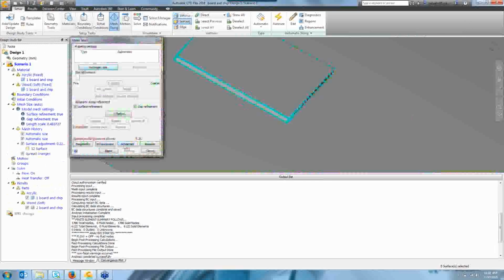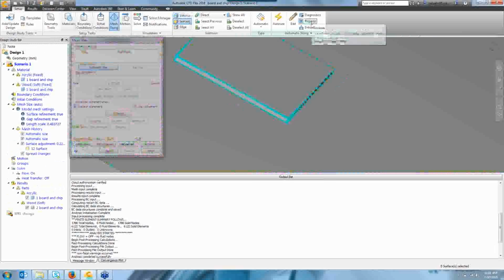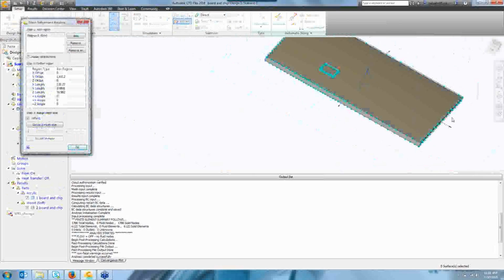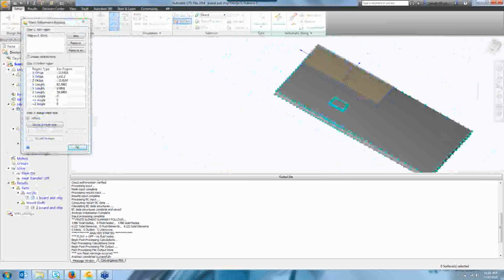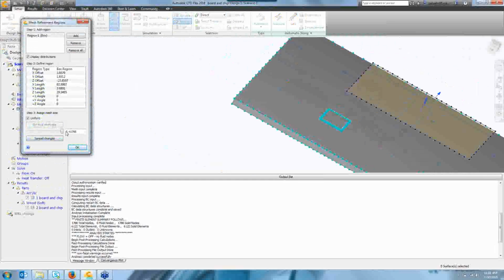Cool. But yeah, everything that you do in the advanced is a global change. If you want to make something more specific because you know that's an important part of the model, you should do it with volume, surfaces, and edges. Sometimes if there's nothing around, using a region can help, because you can always specify that there's actually nothing happening in one of our back corners. Of course, I missed. And I can get the mesh size over there and tighten this if I needed to.